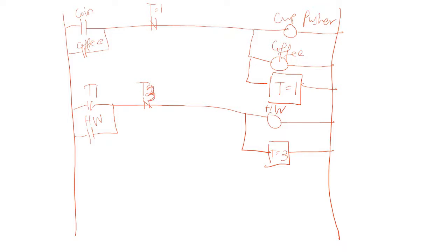Right. Okay, and next it will turn on the motor mixer for 2 seconds. So you need another timer for that. You can use exactly the same design for this round. So add another round. Okay, first it will use the T3 and then it will turn on your mixer motor.